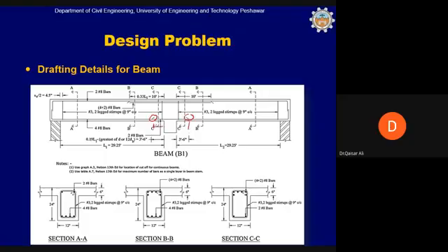These 2 cuts tell you that the reinforcement here is 2 bars. Though wherever there are 4 bars running in one layer, it is not advisable from my point of view that you do curtailment. But anyhow, just to show you that curtailment can be done and is possible in this manner, very close to this interior support, because very close to the support, positive bending moment is almost 0.